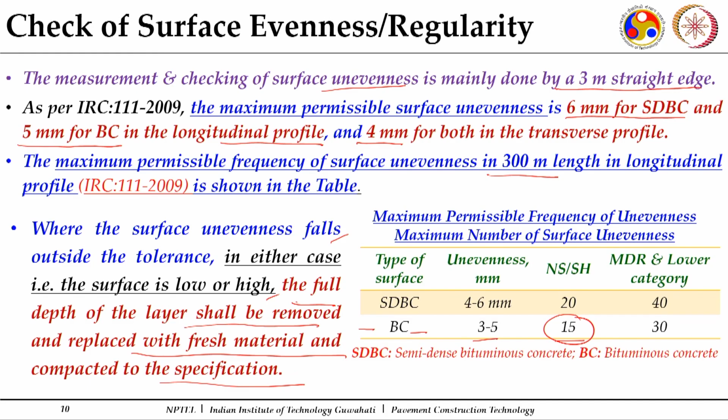Now, this, as I mentioned, becomes very challenging. So, it is very important to ensure this prior to the construction of it. We need to ensure the levels of your base courses. There itself we will see whether the base courses are having positive tolerances, then we will warn them that the wearing course should not go with negative tolerances. And in addition to that, we have to make this continuous check for your surface evenness.